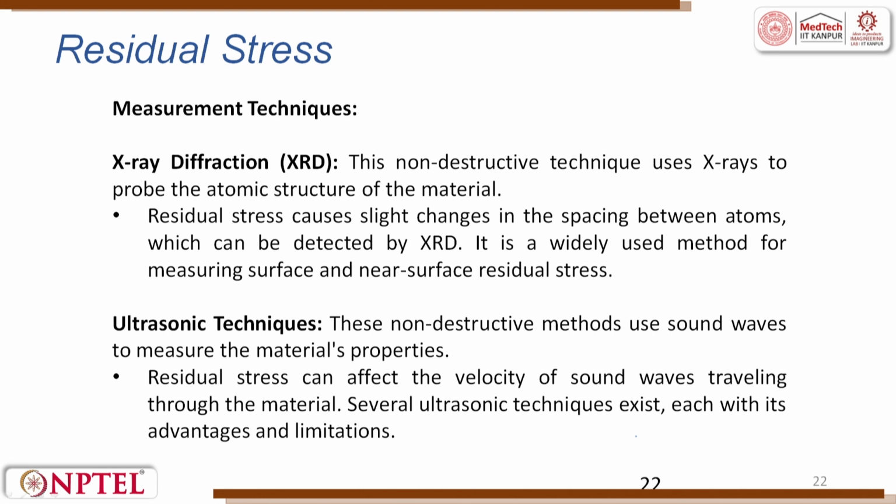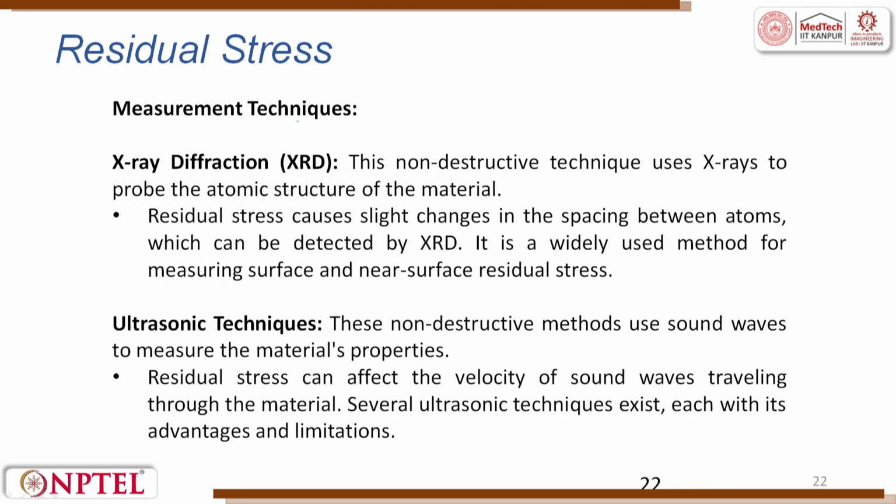How do you measure these residual stresses? Compressive stress can be measured, the tensile stress can be measured, shear can be measured. The residual stress, how do you measure? It is not a straightforward way of measuring the residual stress. There are several non-destructive techniques which are used in measuring. Again I told you there are type 1 residual stress, type 2 and type 3. Type 2 and type 3 to a large extent can be measured. The measurement techniques we use are XRD and ultrasonic testing.